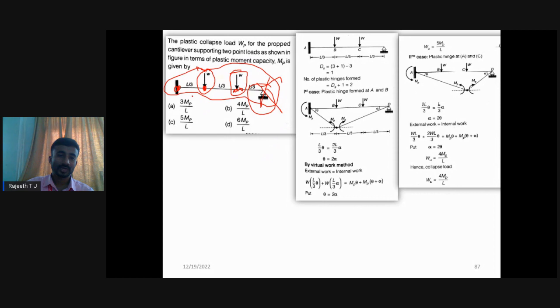What I am supposed to calculate here is, I need to go with mechanism 1 and mechanism 2. First mechanism I can go with by considering this load. Second mechanism I should go with considering this load. That means the deflection under those loads we are supposed to consider. If you consider the first case, here they considered the deflection under this load. They wrote the mechanism like this. Here also MP theta, MP theta. We should calculate carefully, this is what I want finally. I want this deflection, which we should calculate carefully by using these two triangles.